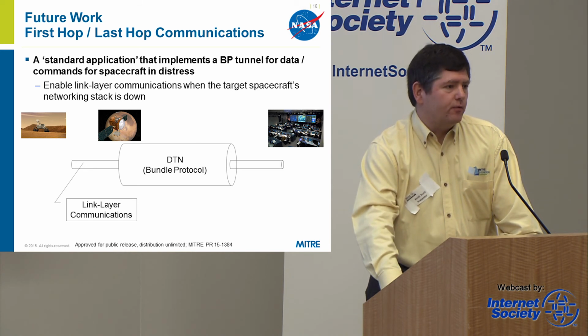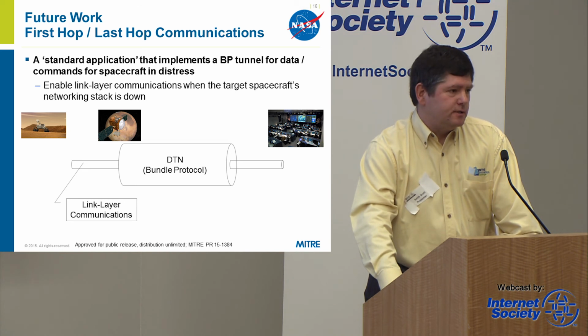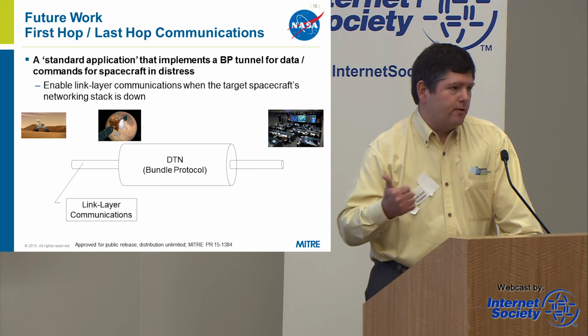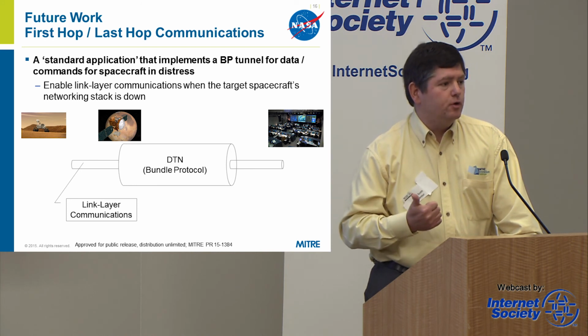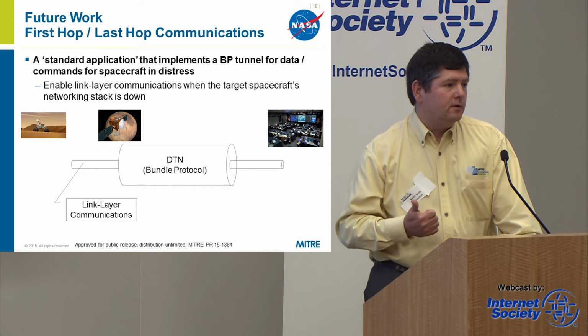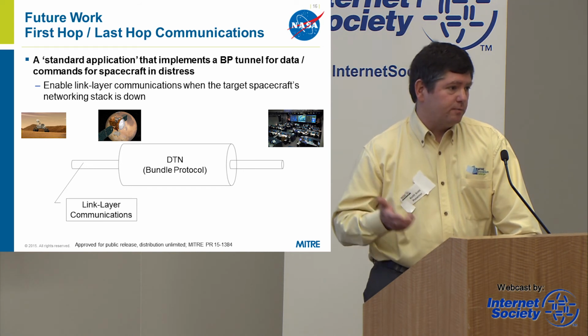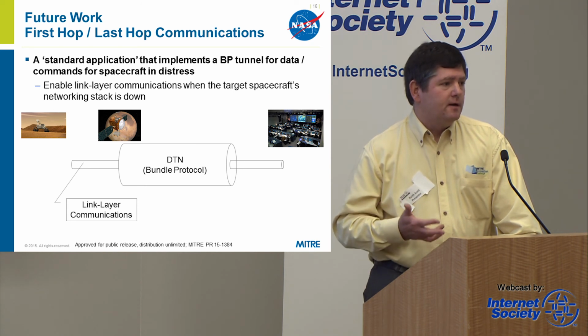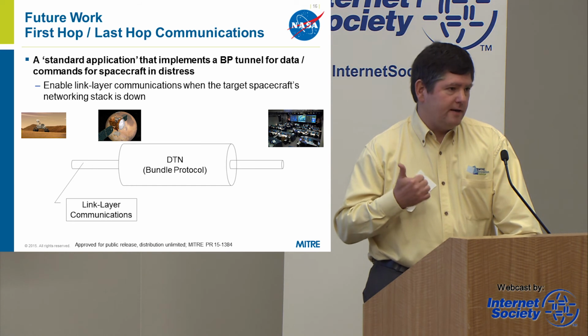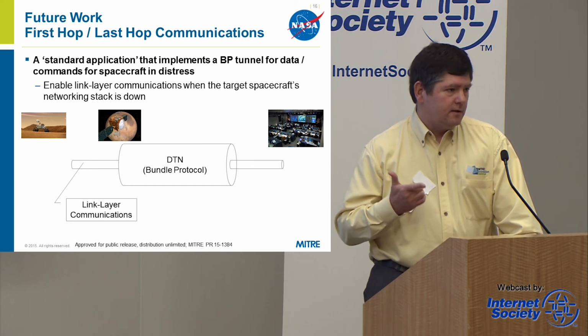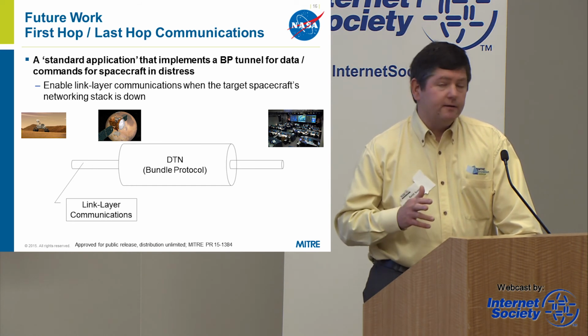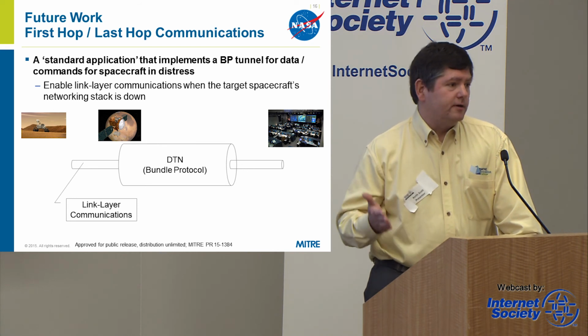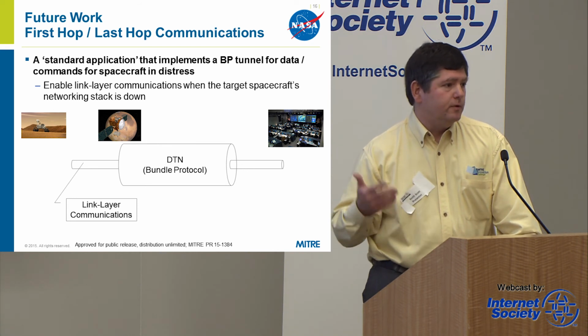So the notion is for emergency command, you would send a bundle to that application that said, okay, guess what? You're the penultimate spacecraft. Somebody who's your link layer neighbor is in trouble, and I need you to radiate this kind of frame at them, and maybe that spacecraft has multiple radios or an SDR that it needs to reconfigure in some way, but I need you to start radiating this kind of link layer frame at them, this many times per second, at these times, in order to get their attention and tell them to go into safe mode and reboot or get restarted.